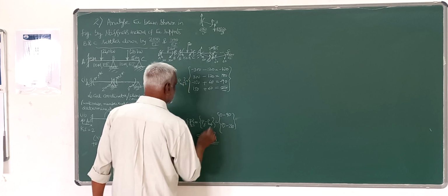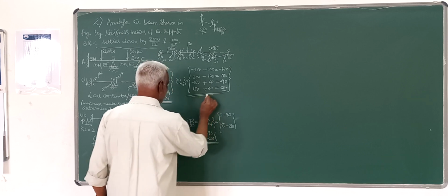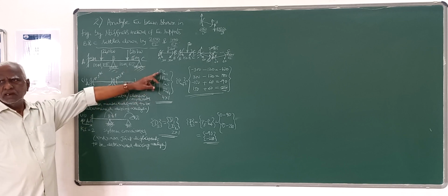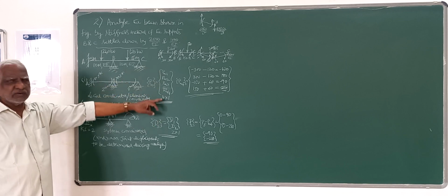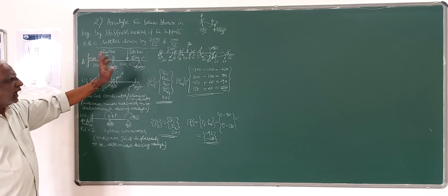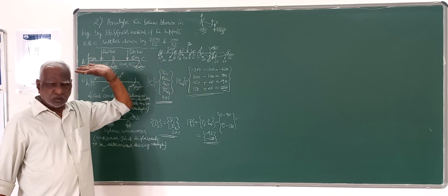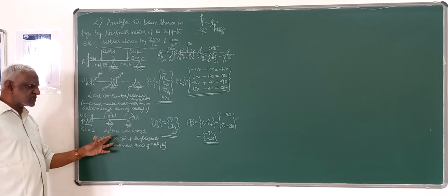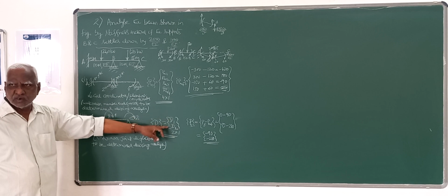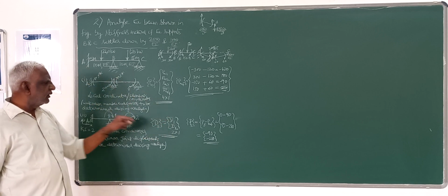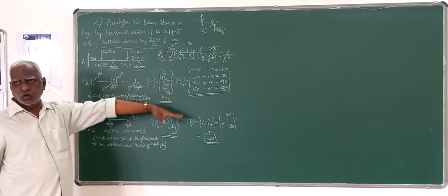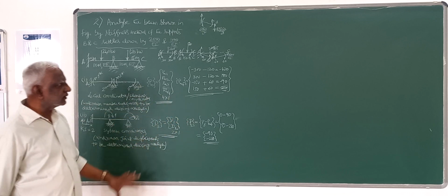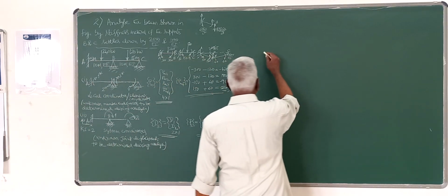So this much calculation you can do in the first 2 steps. In the first step, you have to indicate the element coordinates and the internal member forces which you have to determine, along with the fixed end loading. Similarly, in the second step, you have to identify the system coordinates, that is, the displacements you have to determine, along with the external and equivalent loads which are acting, which you also have to calculate. So these are the 2 steps which we have to follow.